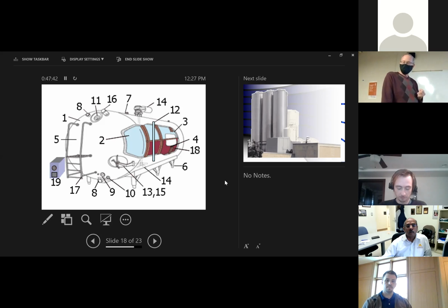What's going to happen inside that tank? I'm going to be removing the liquid. I'm creating a vacuum in there. If no air comes in to balance it out, what happens to your tank? I watched a guy suck a bulk truck in one time. He didn't put a vent on the top. He got talking to somebody and forgot to put the vent on, started pumping off, and literally sucked the walls in. That's what will happen if you don't have proper venting.